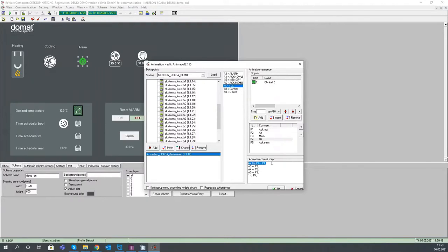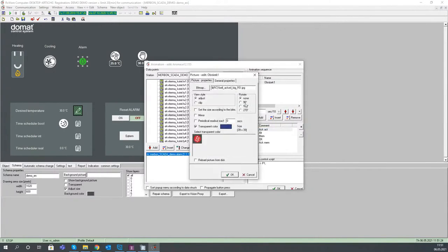So for the end of this script of animation, you can do more complex conditions. For example, this one, and there is A4 and A3, and it means that alarm is active and also acknowledged. So it will generate the first phase. It will connect with the first phase, which is called active and acknowledge. And for this state, we have defined this nice image. So this is how it works.